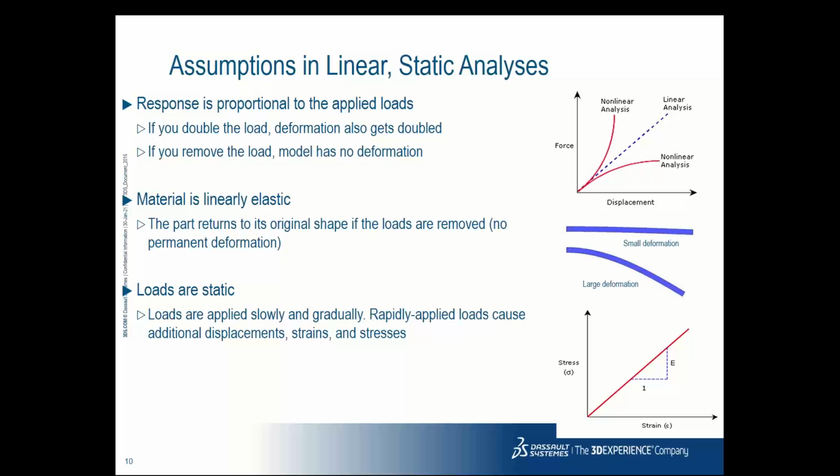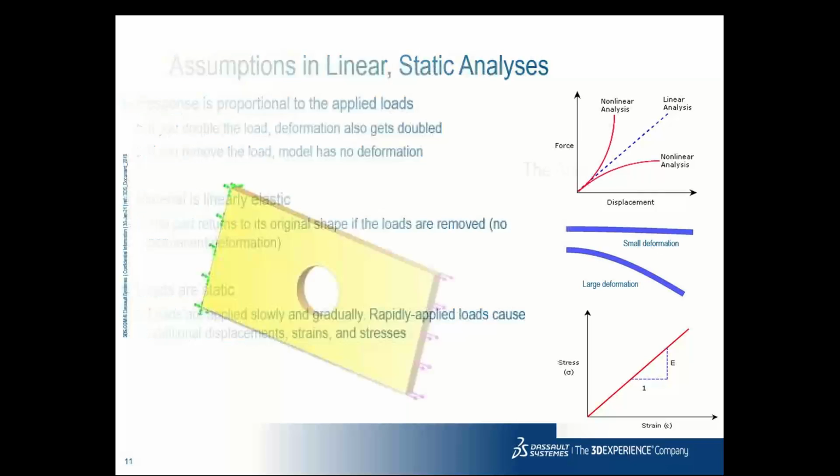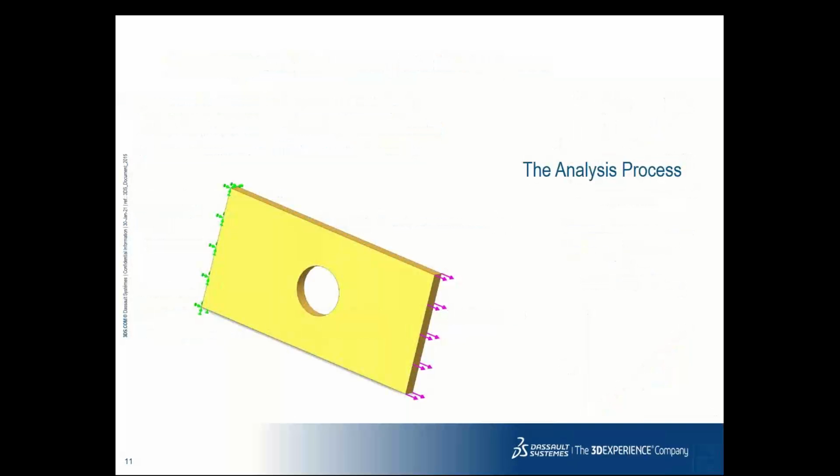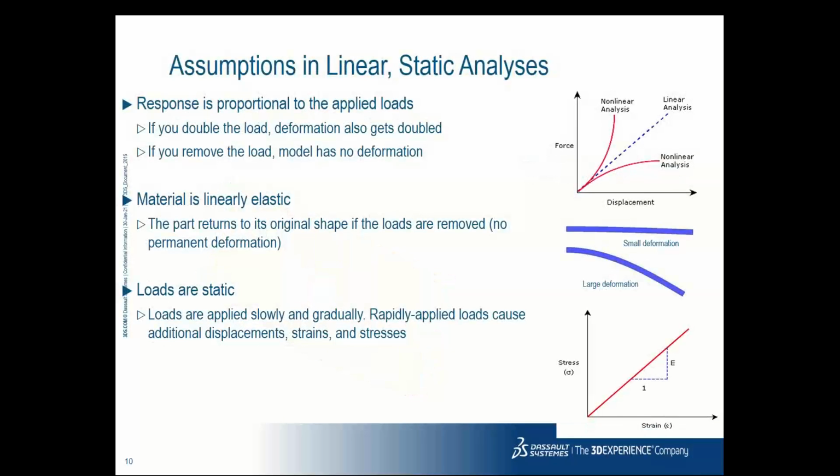Linear means the material is linear in behavior, so after removal of the load, it will regain its original shape. The material is elastic in nature, it won't enter the plastic zone, and the loads are static in nature. These three are the assumptions of linear static analysis. So I will walk you through the basic analysis process.